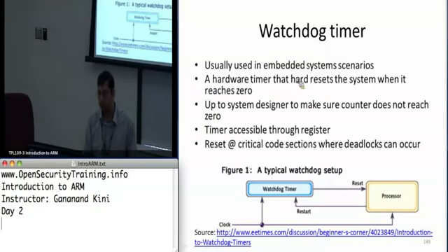They basically say, if the system is in a consistent state, either an IRQ or an FIQ will fire every so often, and it knows whether the system is consistent or not, and then it resets the watchdog, and so the power reset doesn't occur.